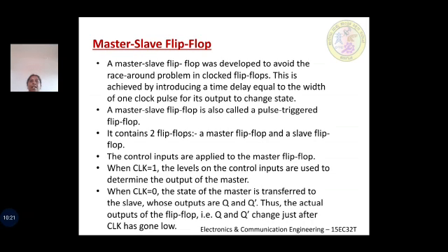It contains two flip-flops. One is the master flip-flop and the second one is the slave flip-flop. The control inputs are applied to the master flip-flop. When clock is equal to 1, the levels on the clock control inputs are used to determine the output of the master.